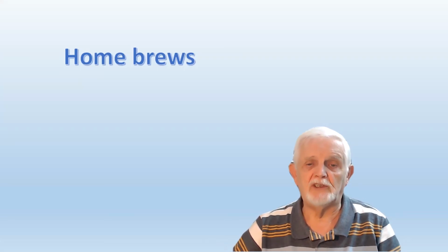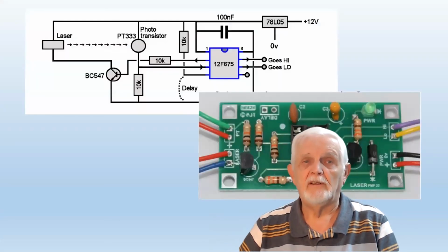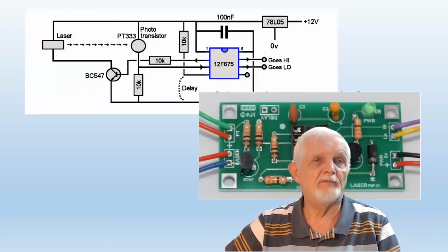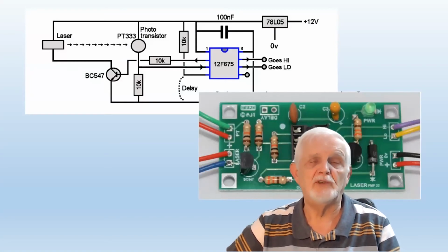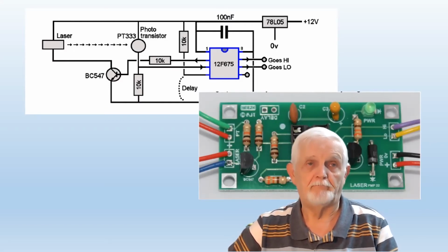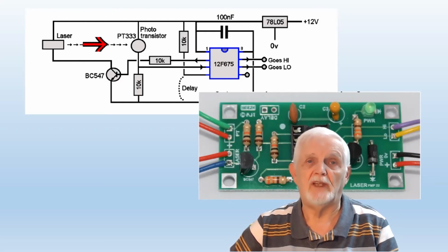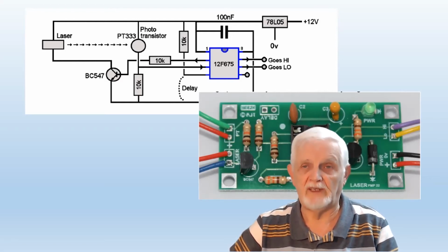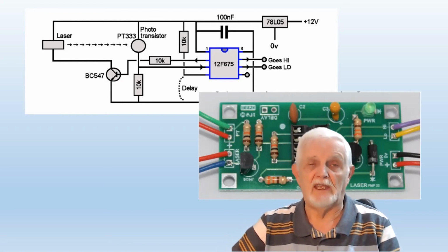And for that, we're going to use the laser and phototransistor that was used in the Laser Totty. A laser emitter sends a beam across to the phototransistor, which changes the light level that goes into the PIC in this particular example, and it began life in Veroboard.